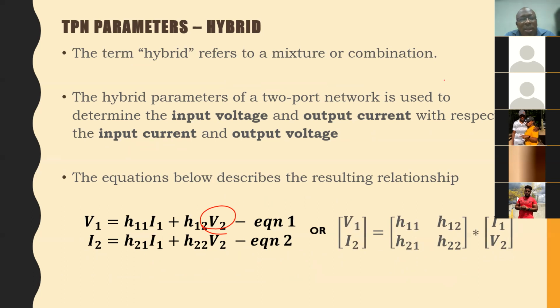You see H22, H21? I'm gonna say H21. Okay, so if I want H21 from equation 2, what would I make 0? You'd have to make V2 0. Okay, so if V2 is 0, what is H21? Well, H21 now would have been V2 0. That means your short circuit V2, then it would be V2 over V1.